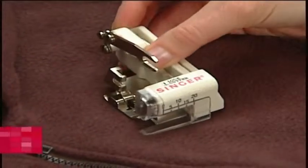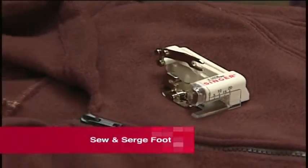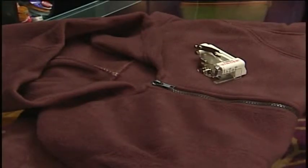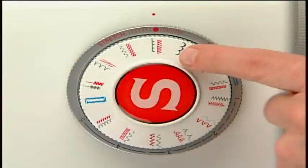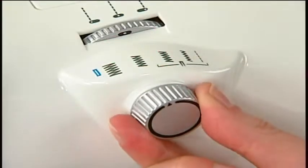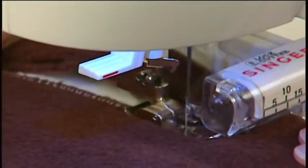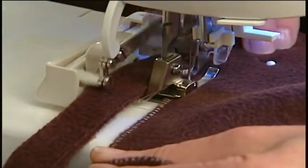The sew and serge foot, also known as a side cutter, trims excess fabric while sewing. The machine is set for an overedge stitch with the width set at its widest setting. The seam is sewn, finished, and trimmed all at once.